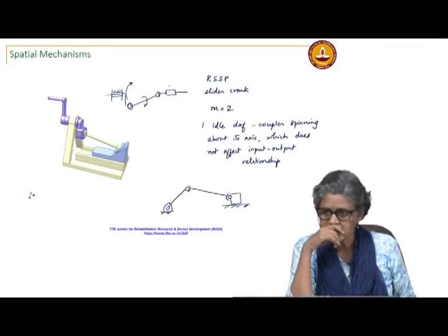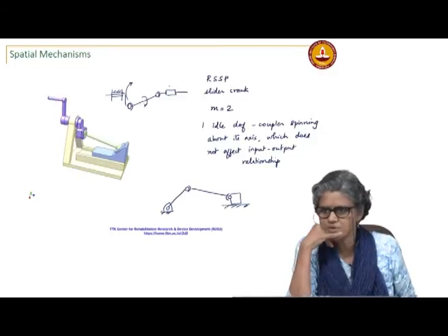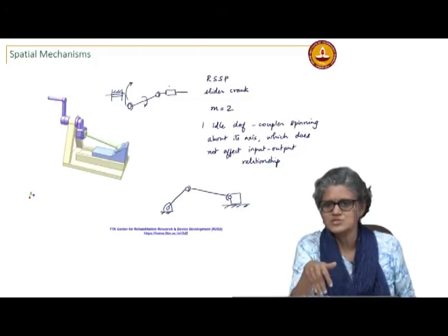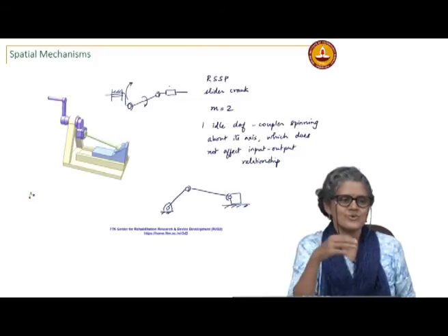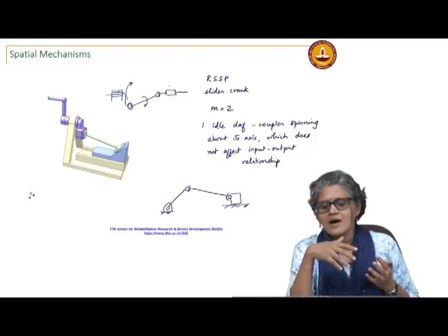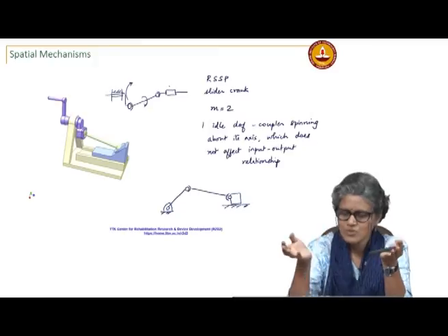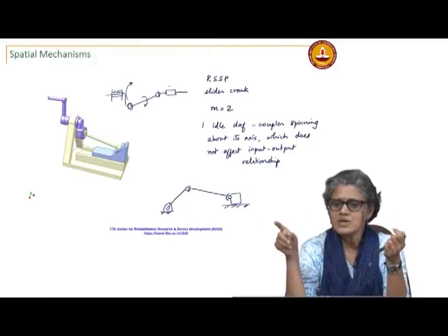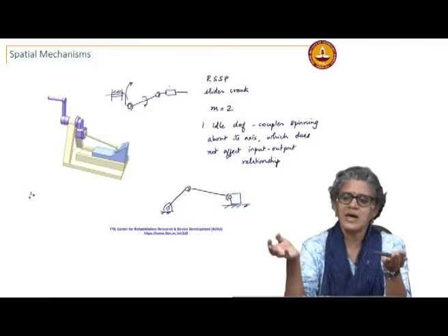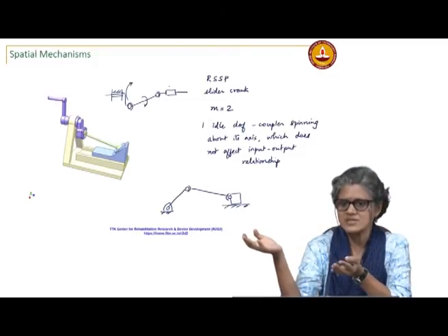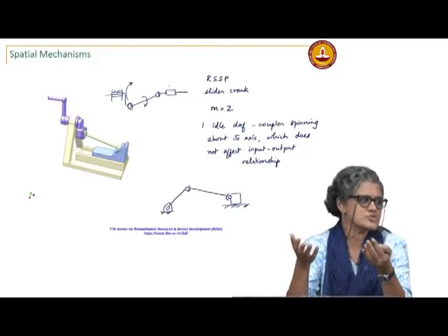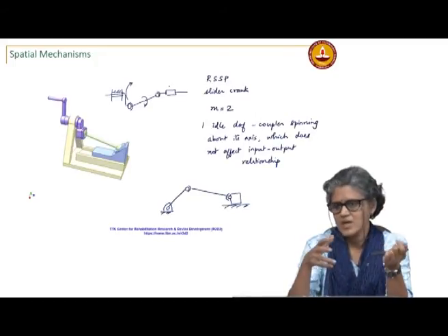So that will become a 3-link mechanism, right? In spatial, 3-link mechanisms are possible. That's exactly what you did here. With special geometry, you can always play around with the geometry to come up with something special. Like you have your 4 bar: typically your coupler has complex motion, but with a parallelogram linkage, your coupler has only translation. You can always play with geometry. That's always possible.